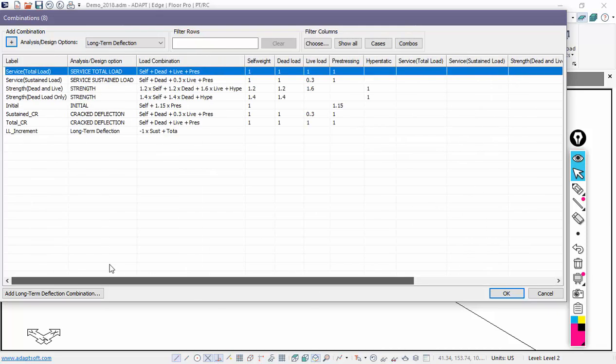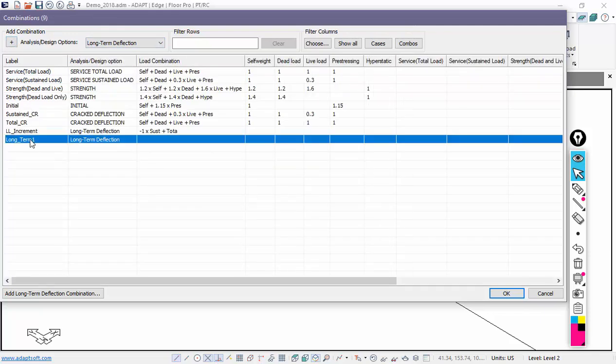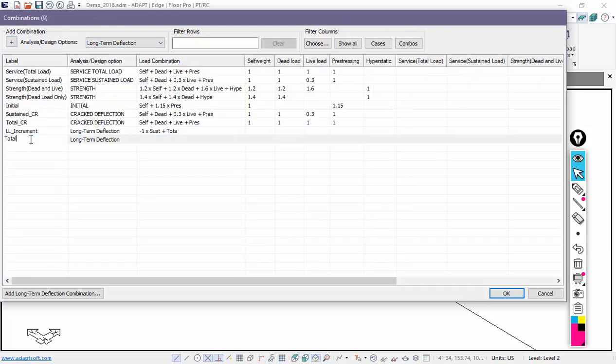And then my total long-term deflection will also be tagged as long-term. Again, I want to combine the results. And we're going to say total long term is going to equal this creep factor. In this case, we just have to apply a factor of 2, for example. It might be something less depending on whether you have compression rebar, whether you're predicting it at some day in sequence other than, let's say, in service condition, maybe 5 years or beyond.